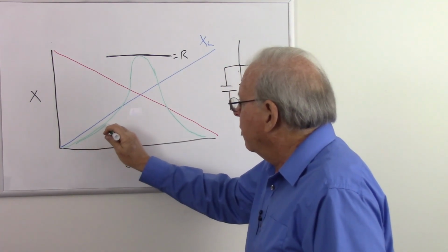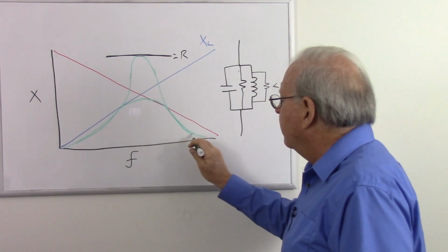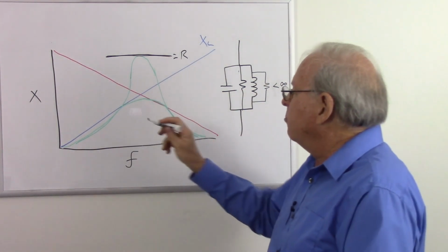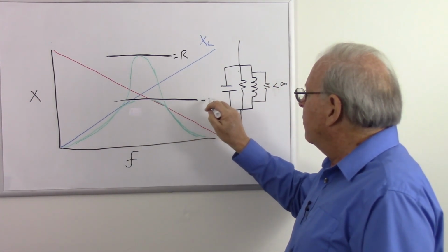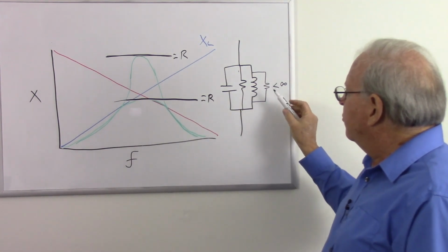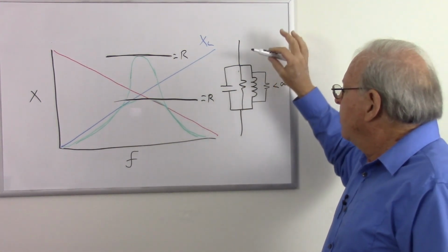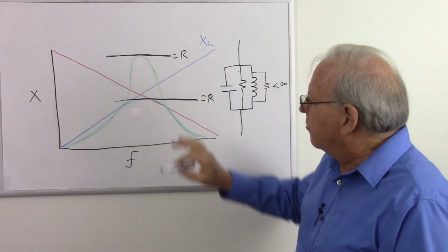So it's going to go up, and then it's just going to heel over and go back down. So I add more resistance in parallel, my maximum impedance gets lower and is still equal to whatever my total resistance is. Once again, remembering that these are in parallel, so adding resistance decreases the resistance because they're in parallel, so that brings down the maximum impedance.